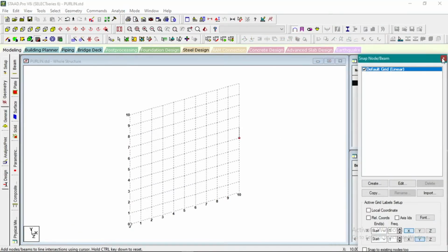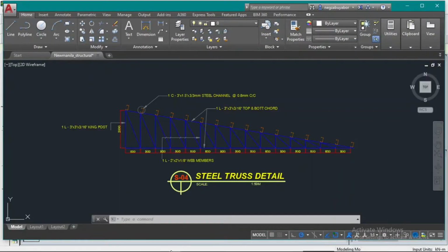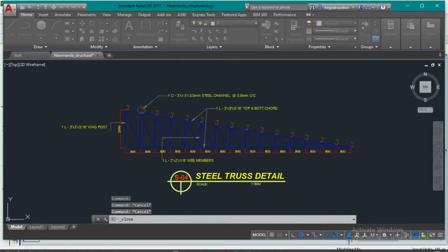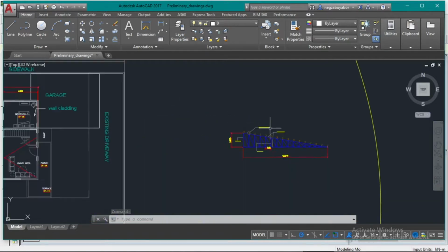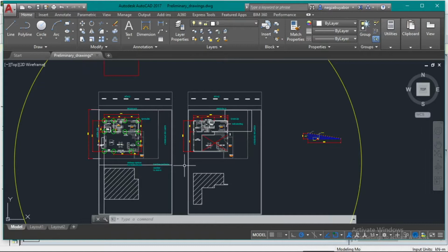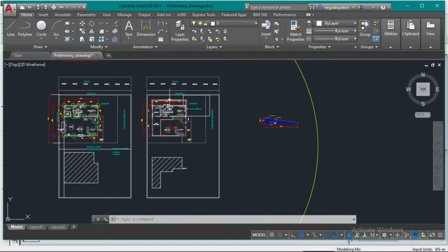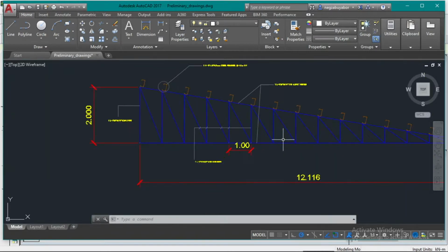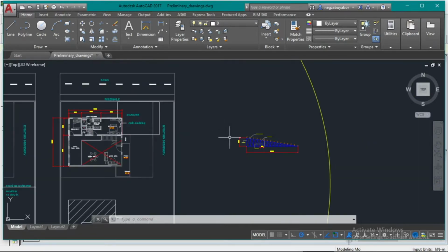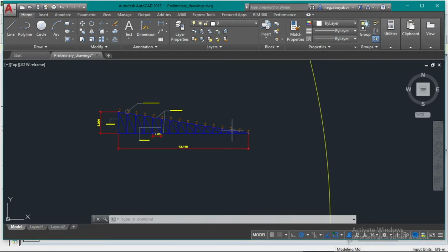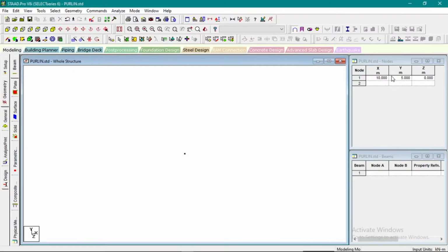Okay, so sa Purlin natin, let's go to the member. Okay, so sa Purlin natin, spacing is 0.8 meter. Length niya is, since it's 12.6, and then yung truss spacing natin is I'll be using 3 meters sa truss spacing. Okay, so let's go to Purlin design.